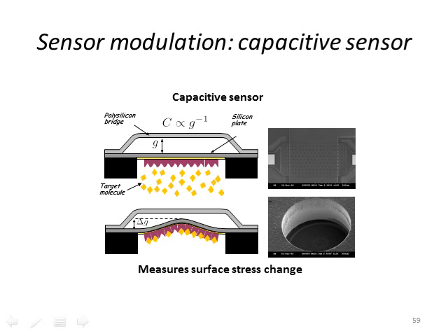Now, an example of doing this is something that I did many, many years ago, which is to design a capacitive sensor that changes when molecules bind on one surface. On this top plot, you will see a capacitor. The upper capacitive plate is located in gray, and then we have a lower capacitive plate, and the separation distance is G. These are all made in the nano lab.